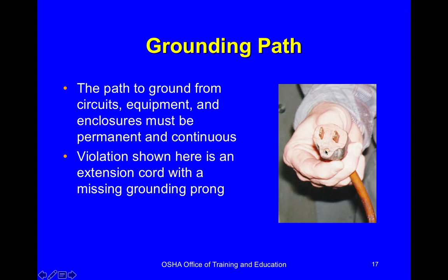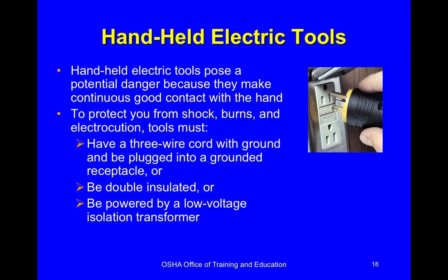In this case, it's broken or it was taken away. So if that is missing, you don't have the path to ground. It's been interrupted. So if you plug in a power tool that relies on that, and you have an electrical leak in the tool, now you're going to have a problem. Okay, so that's a no-no. Has to be replaced.